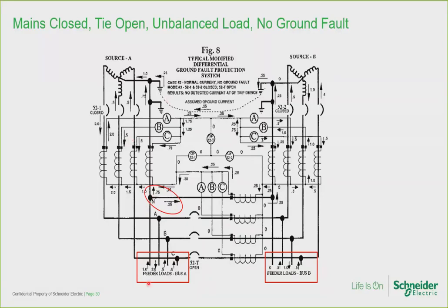Okay, back to the neutral current of bus A. Please notice at the intersection, the red circle, that 0.25 per unit of diverted neutral current flows to source B. It reaches the source B switchboard and, if you will, it turns left at the intersection to flow up to the source B neutral terminal, 0.25, there it is. Upon reaching the neutral terminal, the diverted current then flows through the system bonding jumper to the ground bus. This is a system bonding jumper.